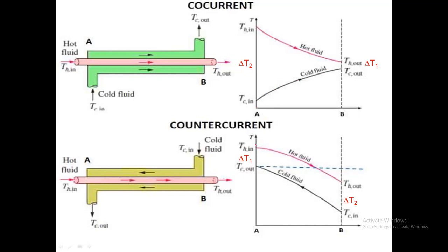However, you interchange the delta T1 and the delta T2. You have the same orientation as to the hot fluid and the cold fluid in the two directions of heat transfer. However, it's the delta T1 and the delta T2 that you interchange. So always remember that since hot temperature is higher than low temperature, your curve for the hot fluid should always be on top of that of the cold fluid. That way you will not be confused.